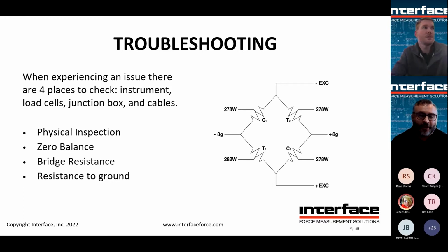Yeah, I think a final comment too, mechanical, assuming the system works, you can assume it should continue working. And if so, then maybe one of these issues, but also look for mechanical, parallel load paths. Imagine if somebody jacked up one leg a little bit to do something and they forgot to remove the jack, right? Or say something's binding, something shifts a little bit, and now you've got some rubbing or something. So there are mechanical things to be checked too. And a lot of times that might be the issue.